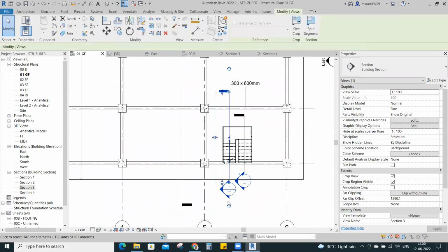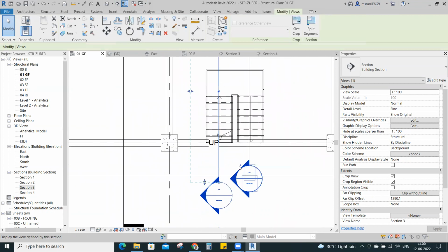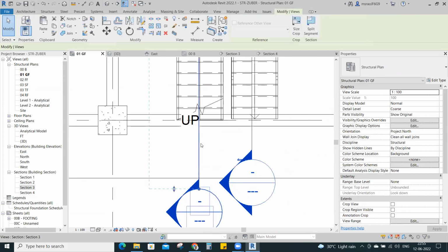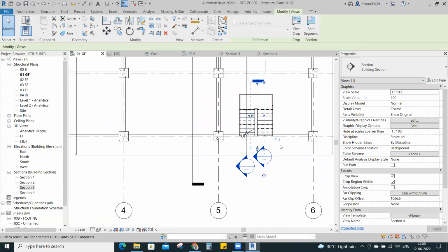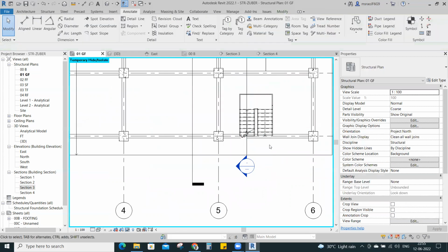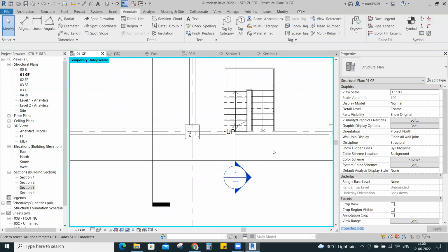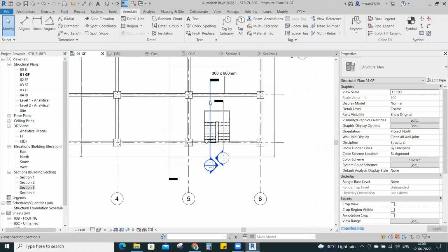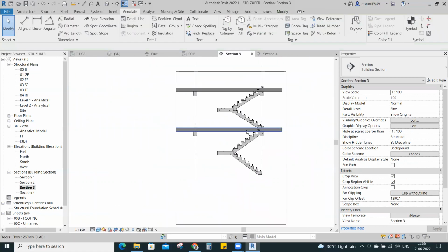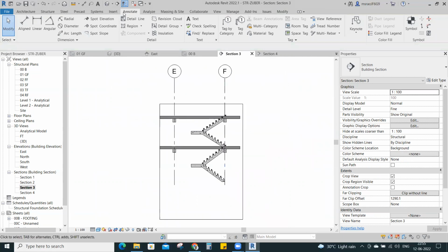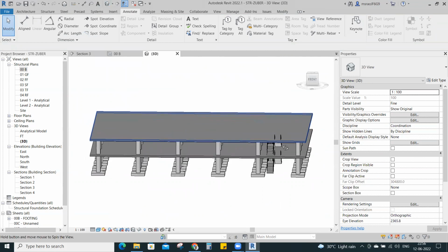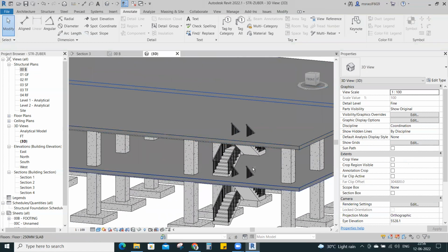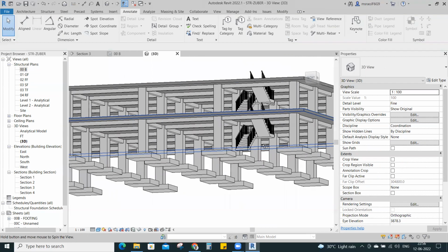If you want to click it, go and flip. Just flip arrows. Select and see, we are unable to select this. Go to hide, HH, select and HR means reset. If you go and select here, you can see the staircases. Up to this fine, right? But when we see it in 3D, we should have the slab opening at the staircase area.